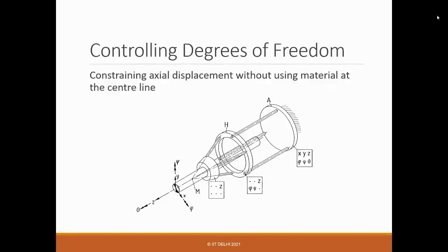So that's the idea. In this case, suppose you want to constrain axial displacement without using material at the center line. Suppose this is the rod or pin or bar, but at the center you don't have any way to put anything there, or maybe you want to place something else there, but you still want to constrain the X displacement only.